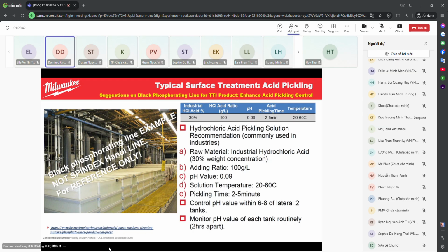But sometimes our supplier needs to apply strong acid cleaning, or so-called acid pickling, before the parts are put into the coating line, so that surface oxidation, surface scale, or any kind of contamination can be removed. That can give us good part quality, but this strong acid cleaning or acid pickling process brings a huge risk of hydrogen embrittlement. So we have a very strong limitation on acid pickling.